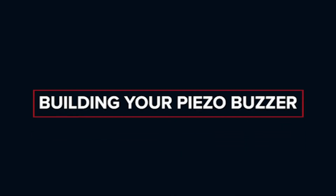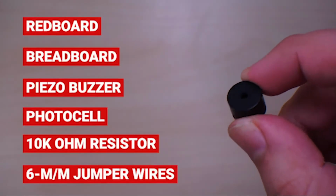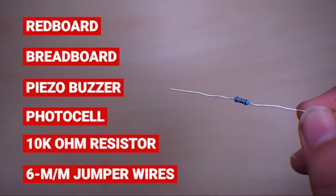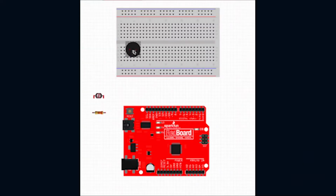Now we're going to jump into how to build your Piezo Buzzer. For this activity, you'll need a Redboard, a breadboard, a Piezo Buzzer, a light sensor, a 10K ohm resistor, and 6 male-to-male jumper cables. To emit sound from the Piezo Buzzer when your surrounding environment becomes dark, follow the step-by-step diagram.